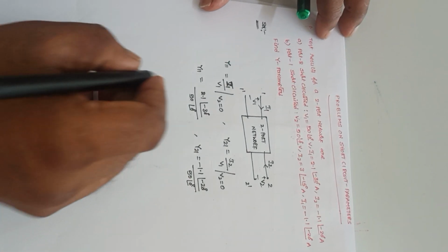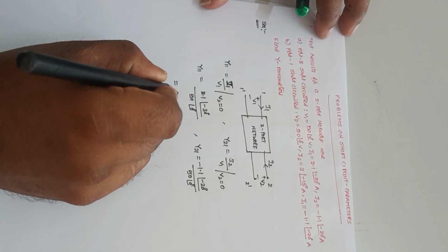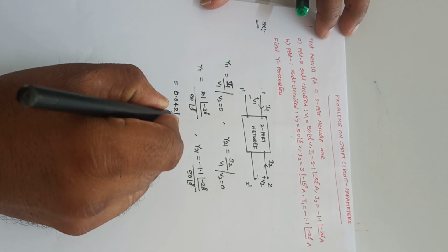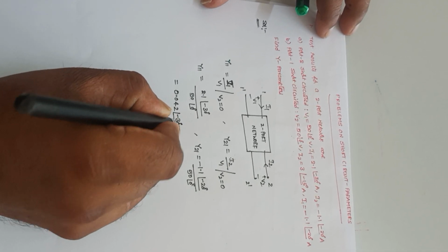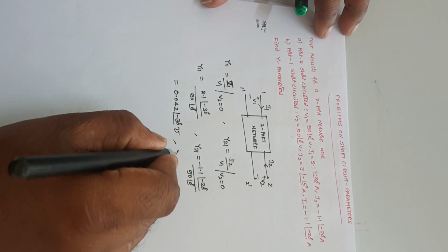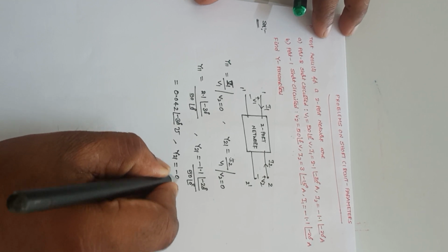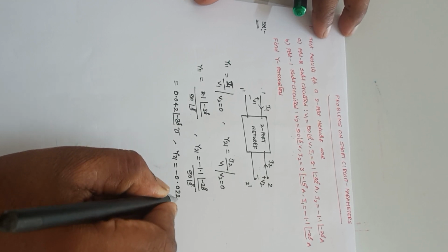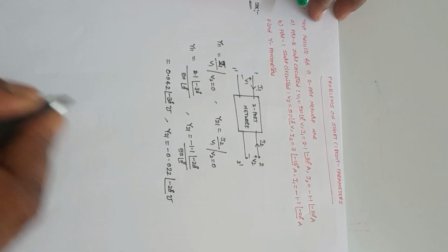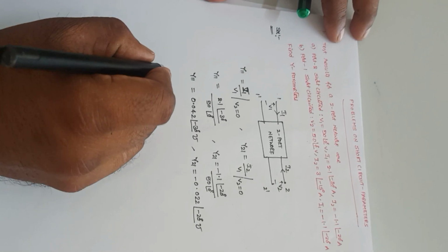If I calculate this value, I will get 0.042 at an angle minus 30, and the units for these admittance parameters are mhos. Y21, if I calculate this value, will become minus 0.022 at an angle minus 20 degrees. It is also in mhos. That is Y11.